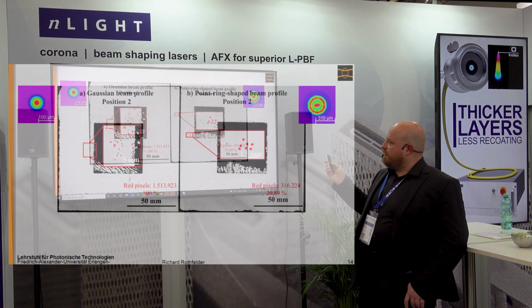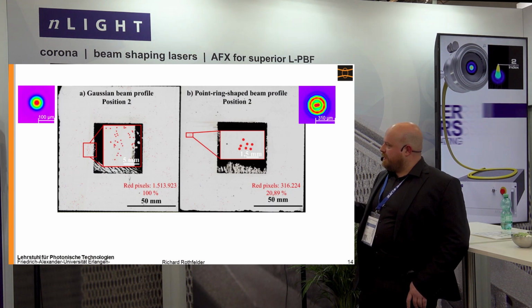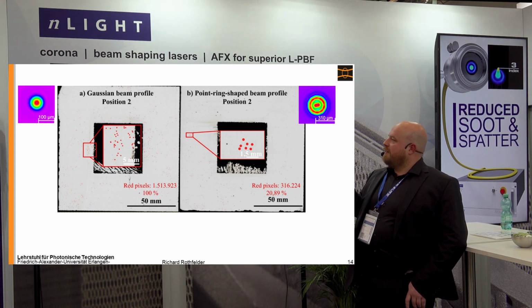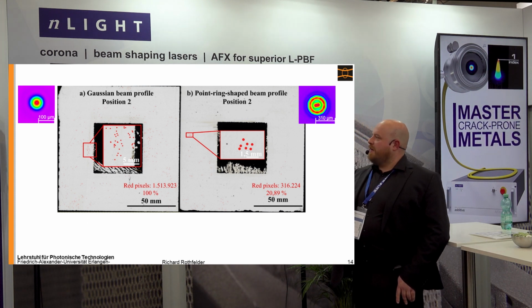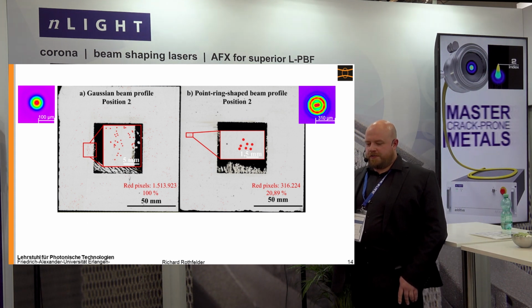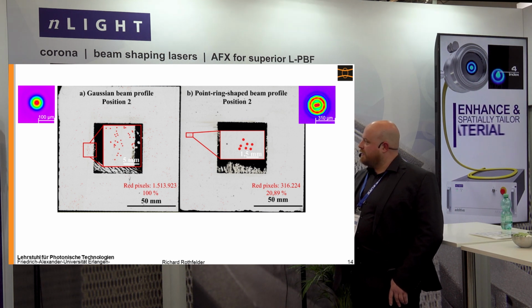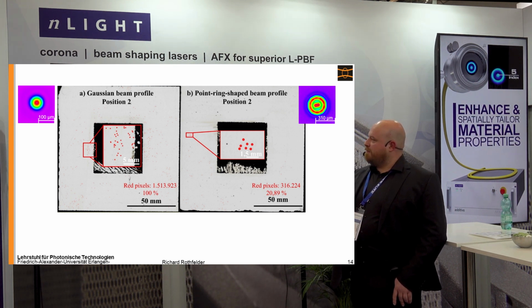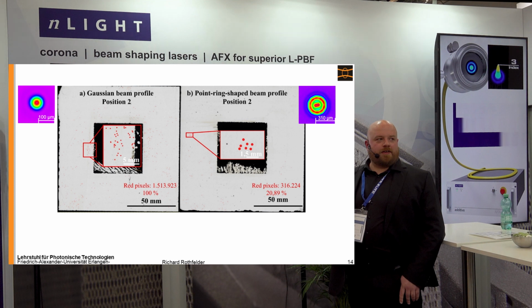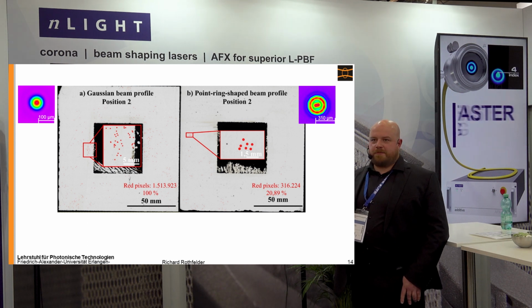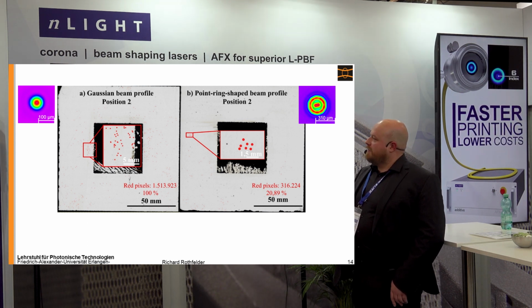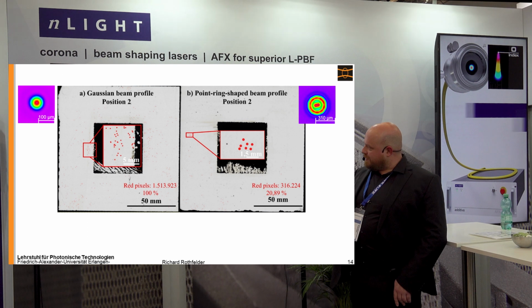To make it a little bit easier and understandable, we just scanned the surface with a microscope, and in every place where we found a tungsten particle, we made a mark with an identical amount of pixels every time, and then just compared the amount of pixels, where around 50 pixels equals 1 found tracer particle.